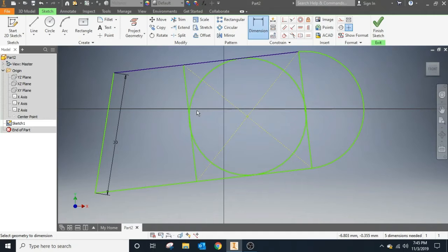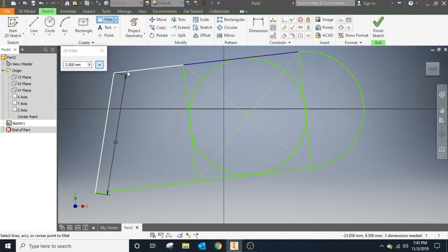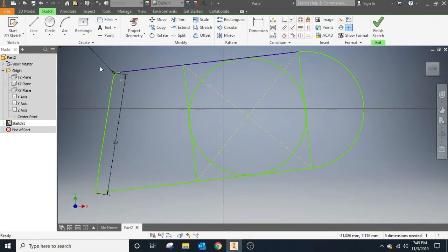So next thing I wanted to go through is patterning. So actually first, let me go through filleting. So we have a corner here, and we want this to be a rounded corner. So what we can do is we can use a fillet. Come up here, we click the two lines that have the corner that we want to create. You see it already is creating it. We can change this to be bigger, 5 millimeters. Let's come down and do this one. So you can see that's a much bigger curve. You can do this on any corners.